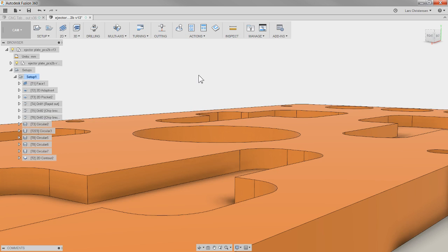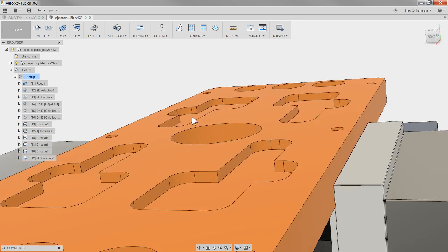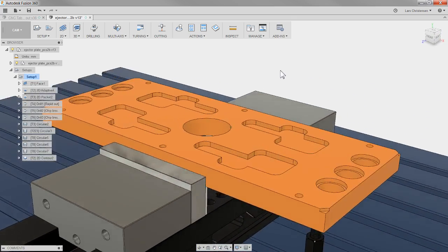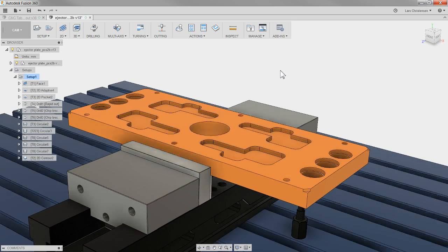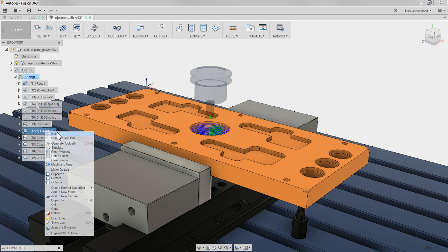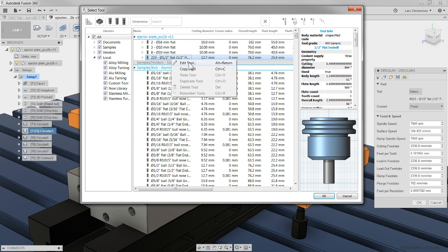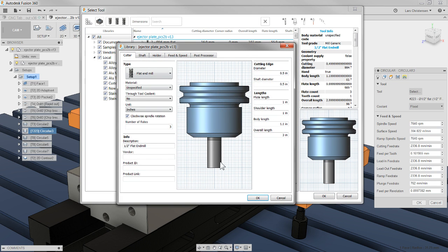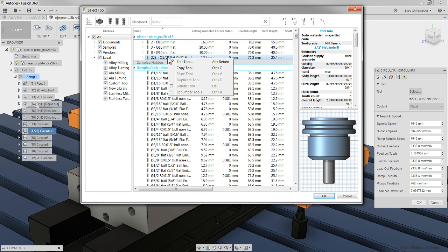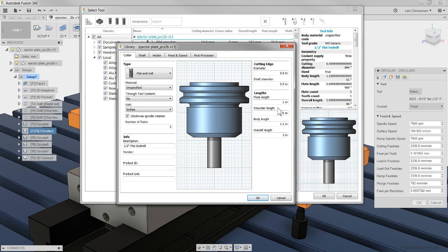to do these things. Now, if you're just machining around a simple block, you might not worry too much about setting up your tool length, because that's this here. If we go and look at this specific tool, let's go back in and look at that tool again. Of course, the information for this tool is all coming from this page here. So I went into the tool library, right clicked, hit edit tool. And all this information over here is what gives that feedback that we are hitting with the shank of the tool, or we're hitting with the tool holder.